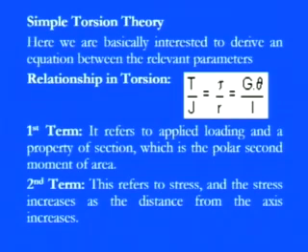Here we are not going for the mass moment of inertia, we are going for the area moment of inertia, and since it is a polar section, we simply divide T by J. Whatever value we get is exactly equal to the second term, which is tau by rho.